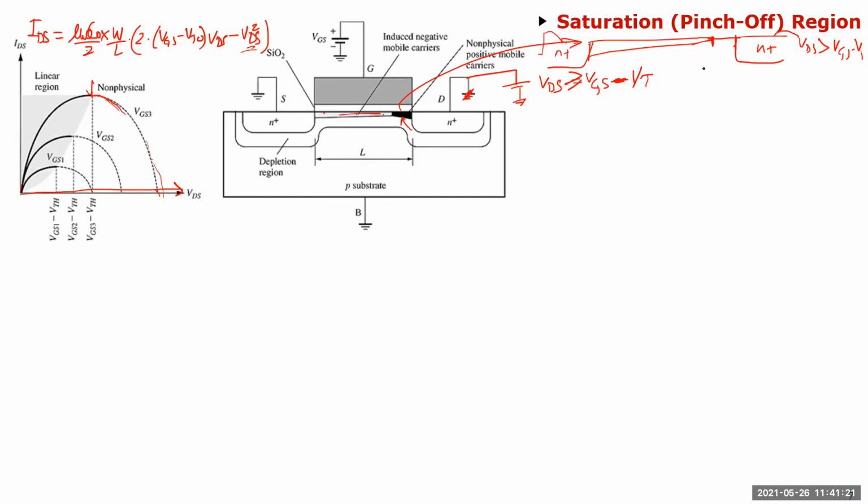Now, the first thing people assume is that if there is no channel charge, the conduction is going to stop. That's kind of intuitive, but it is wrong, because this cannot be treated as a dielectric. You have a varying channel charge, and if you have a varying channel charge, you have to have an electric field. There is motion of charge here. If there was no motion of charge here, then it would be flat.